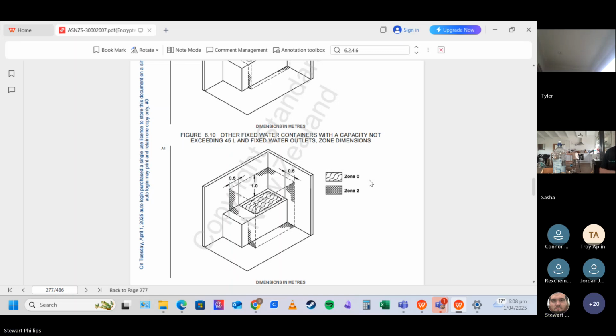Not in a kitchen because, again, steam from cooking. So yeah, your best bet for switchboard locations are somewhere where there's plenty of ventilation. It's not going to have to deal with moisture or any external heat sources or be exposed to the elements unless it's designed for it, like an external switchboard.